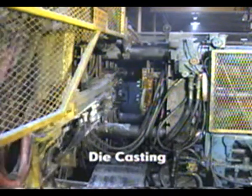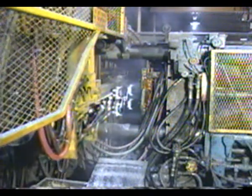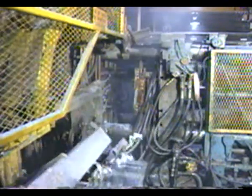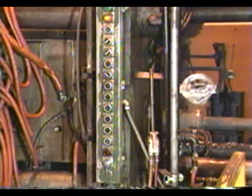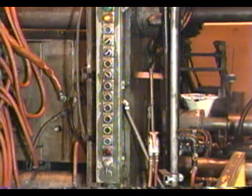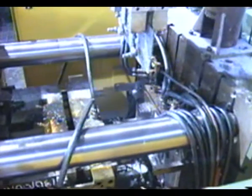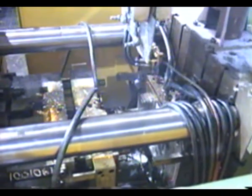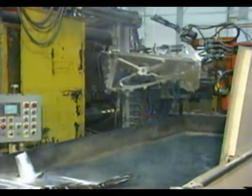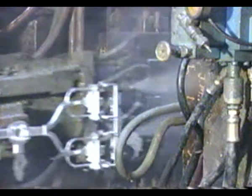Die casting is a rapid, high-production process for simple or complex, often thin-wall, precision parts. Castings are usually small to moderate in size and cast of non-ferrous metals. The molten metal is forced under high pressure into the die of a horizontal, sometimes vertical die casting machine. One die half is attached to a fixed platen, the other die half to a movable platen. Die casting can produce a single part or multiple parts in a single metal charge, also called a shot.